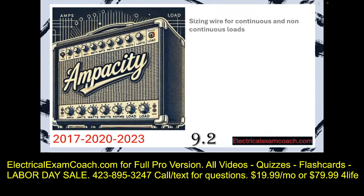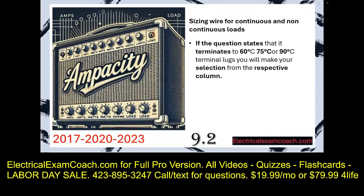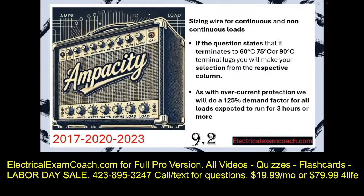In this lesson, we're going to be sizing wire for continuous and non-continuous loads. Let's recap on the basics before we get started. If the question states that it terminates to 60, 75, or 90°C terminals, we're going to make our selection from that respective column under normal circumstances. And the second one is, as with overcurrent protection, like we learned before, we're going to apply a 125% demand factor for all loads that are expected to run for 3 or more hours.